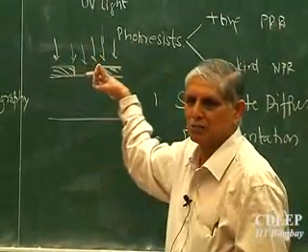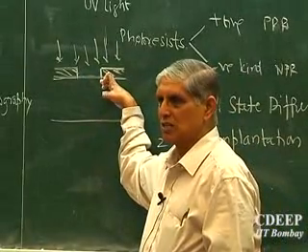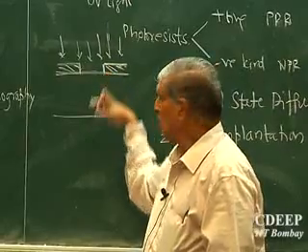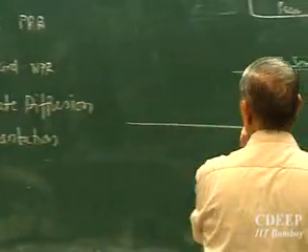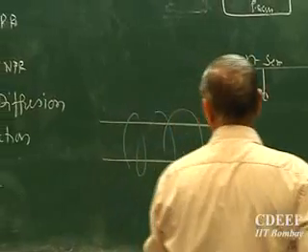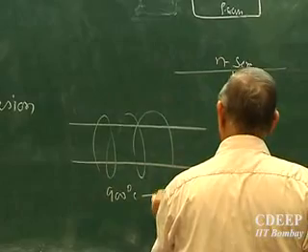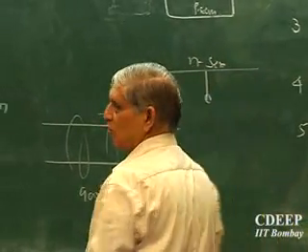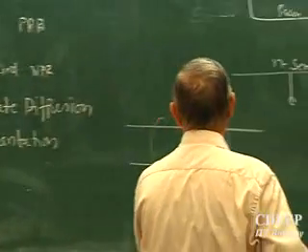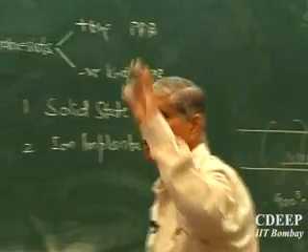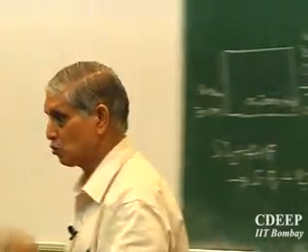So these impurities go in either by solid state diffusion or by implants. First look at solid state diffusion. What we do is, in a big quartz furnace, heated to roughly 900 to 1000, maybe 1150 degrees centigrade, from one side I put wafers inside on a quartz rack. Typically the number of wafers in an actual Intel run will be 200 wafers per run, 200 12-inch wafers will go in the furnace. So you can think what size of furnace they will have. A lot of 200 wafers gets put on a big quartz rack, vertically.